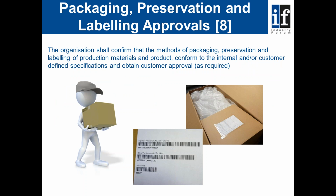At this stage, we would also start turning our attention to packaging, preservation and labelling. And at this point, we have to be very aware of the customer's requirements. So although AS9145 gives us a baseline standard, when it comes to things like packaging and preservation, including labelling, we're going to need to refer back to the customer and either gain knowledge of the customer's standard or actually propose to the customer our standard and seek approval from them in the methods that we have suggested are used. So again, stage 3 activity, but already thinking towards shipping the product, labelling the product and preserving it both in-house and in transit to the customer.